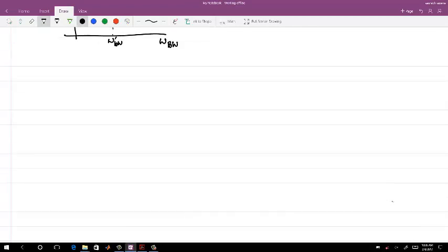For now, you can trust me on this rule of thumb: PLL bandwidth is mostly less than or equal to fref by 10 for all the above analysis we are doing. We can choose lower than fref by 10, but fref by 10 is the uppermost limit. We will see this in detail when we do a digital PLL analysis.